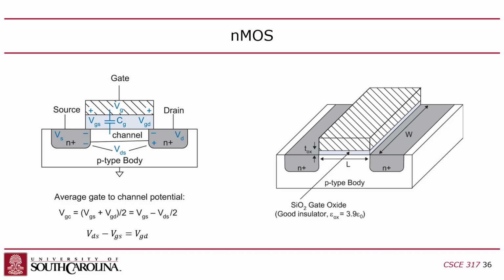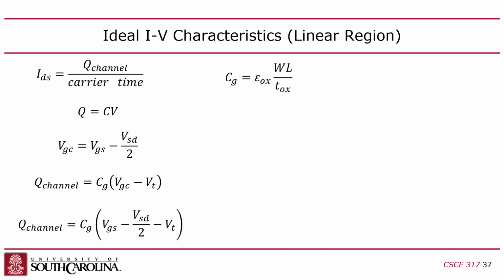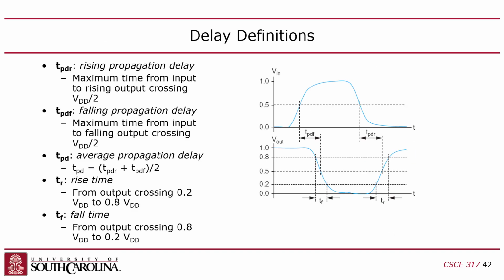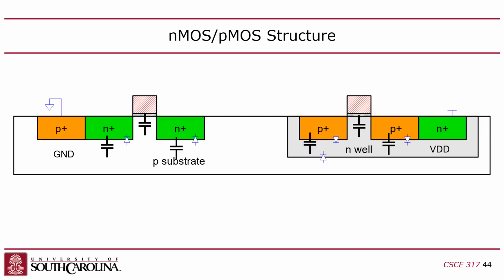And what happens there is they also are capacitors, because when you have a reverse biased diode, as you have here, like I ground, in this case, I ground the substrate, right? So this P is at a lower voltage than these two guys, which means that the diode that's formed from this P to this N is reverse biased, right? So they're not connected, even though they're right up against each other. They're not connected electrically. However, they still form capacitors, right?